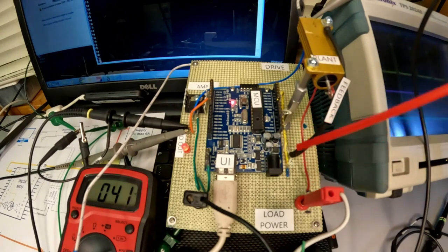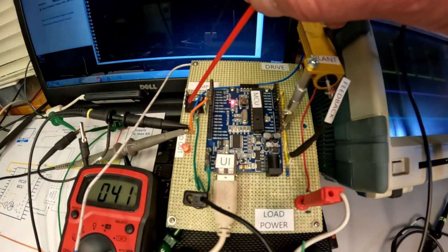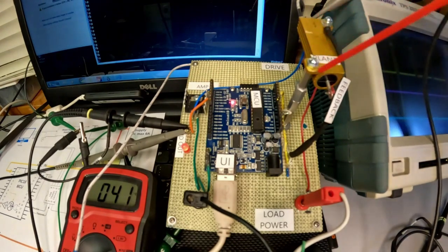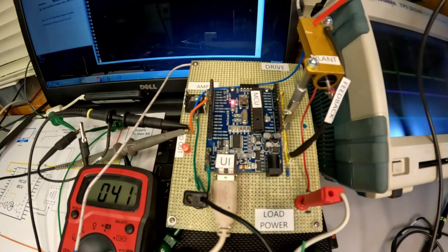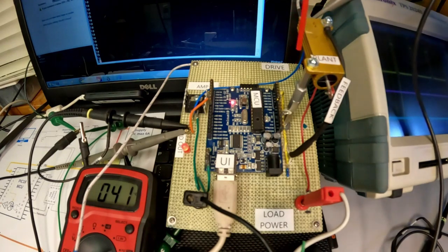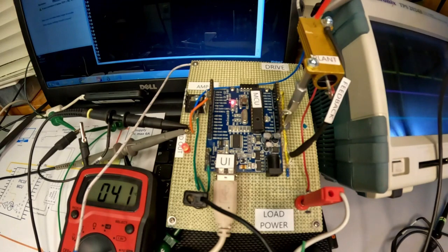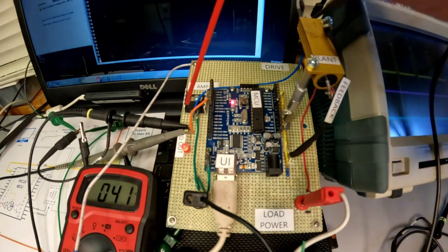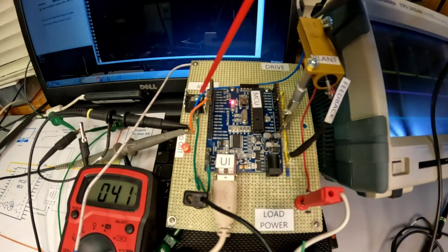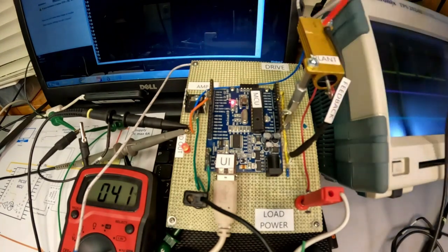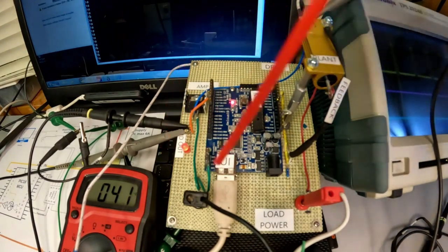So think of this as a switch. When that switch is open, no current flows, so we're not getting any I squared R loss through our 10 ohm 50 watt resistor. Therefore, we're not generating any internal heat, and we get no heat flow through the body of the resistor, and therefore no elevated temperature on the surface. When we close that switch, when we assert the line, or when the PWM signal goes high, the switch closes to ground, and then the current will flow, and this will heat up. So that's our closed loop.